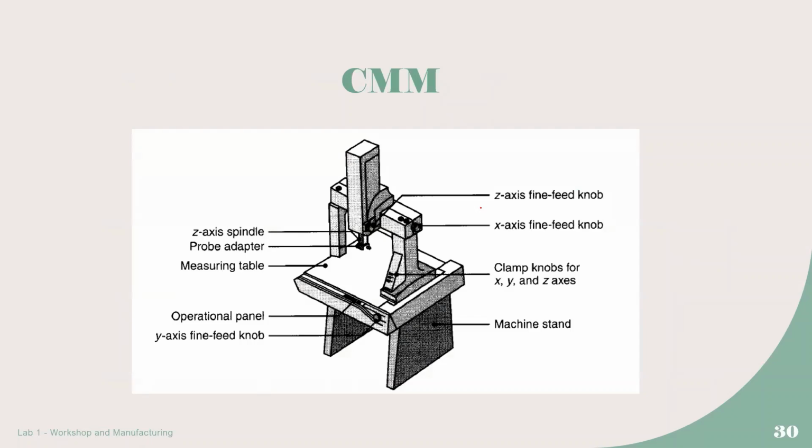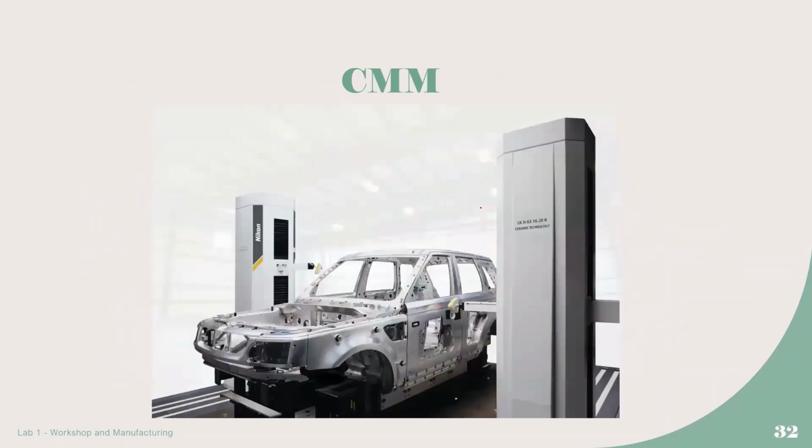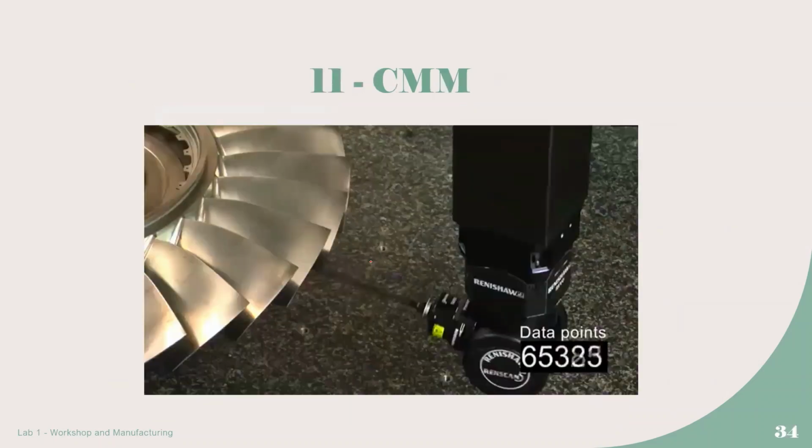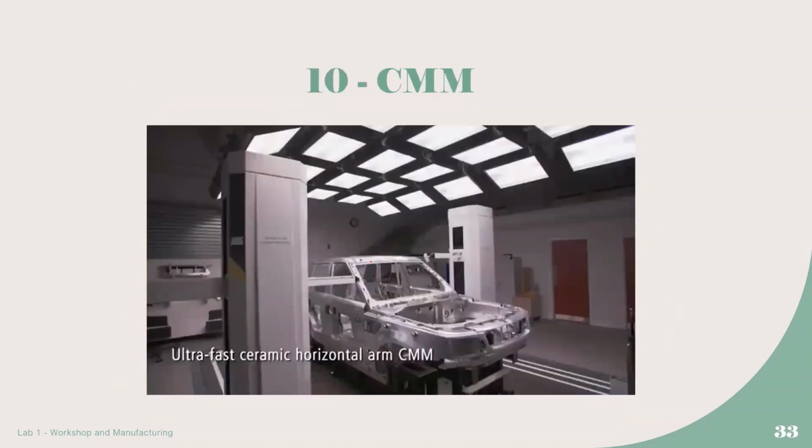Here CMM is illustrated. This one is a really wide CMM machine. You can measure various points with CMM. You can measure the hole diameters, the height differences, the angles, the roundness, and everything. Here we have videos, and please watch them, okay?